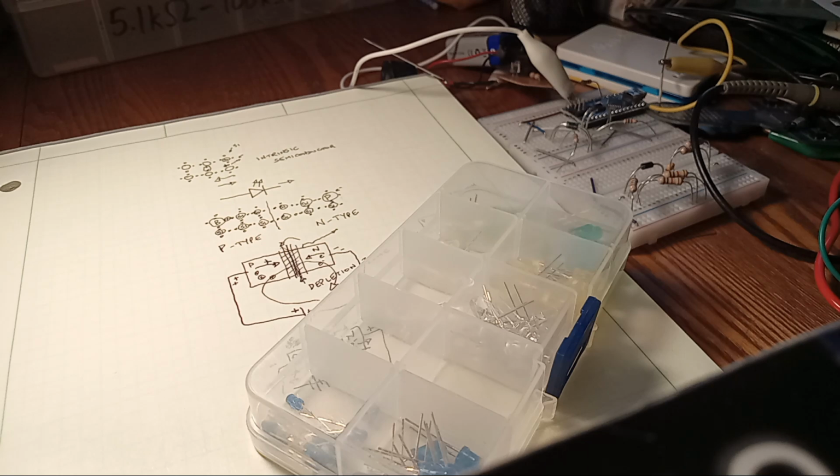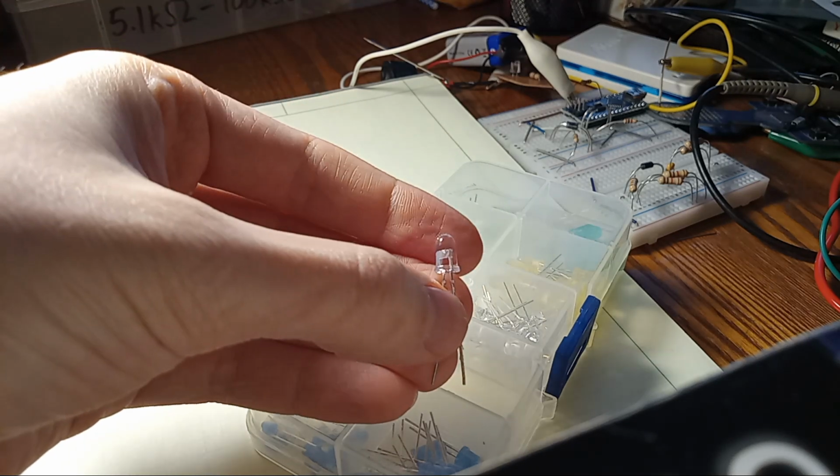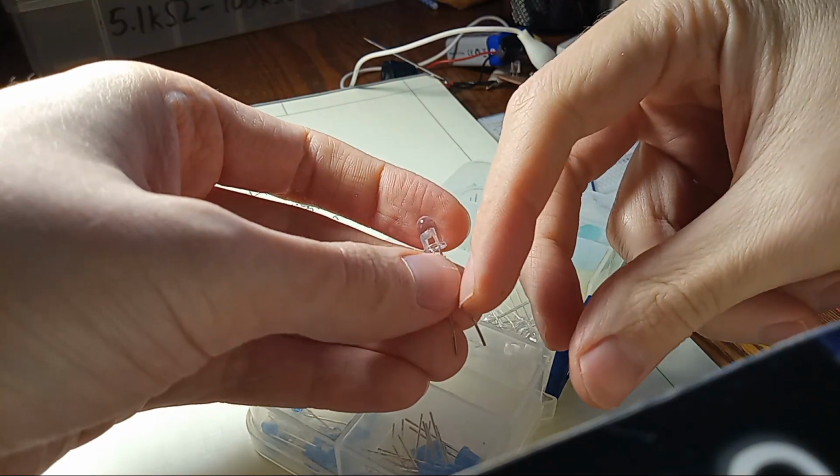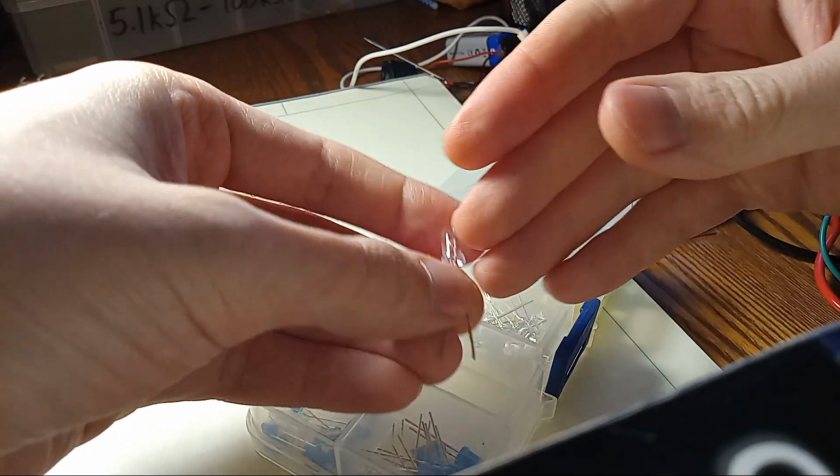So I'm going to give each LED its own 1 kiloohm safety current limiting resistor. If you just want to build things with LEDs, if that's why you're here watching this, use a 1 kiloohm resistor. As long as the supply voltage isn't greater than 20 volts, it'll work for everything. For every standard 5mm LED, that is. Putting 1 kiloohm in series with it will prevent it from conducting so much current that it burns up.